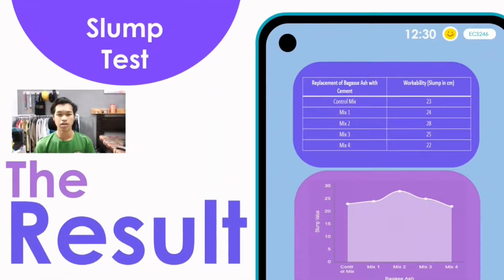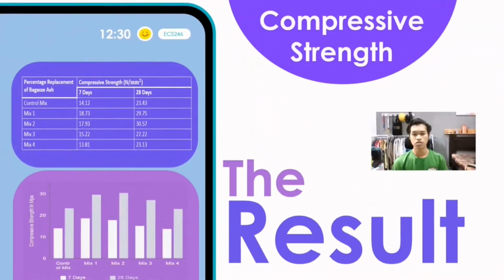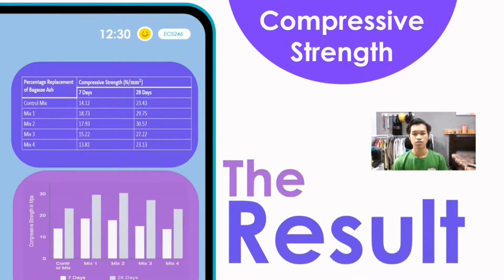Here we have the result of the slump test as the data shows. The replacement of 10% of bagasse ash with cement in mix has a higher slump value. This shows that the mix has a higher workability. The result shows that the maximum compressive strength for 7 and 28 days curing period achieved are 17.93 and 30.57 respectively with 10% replacement of cement by bagasse ash. The results show that the SCBA in blended concrete had significantly higher compressive strength compared to the controlled concrete. It reveals that the cement could be advantageously replaced with SCBA up to maximum limit of 10%.